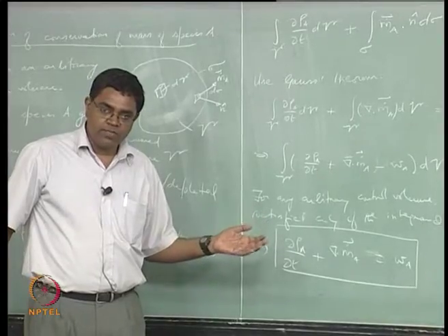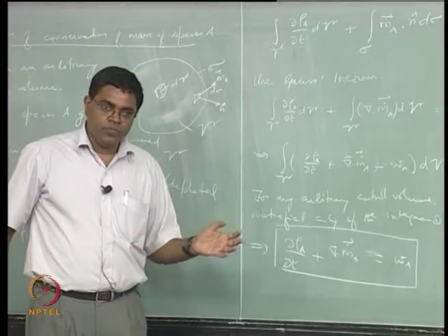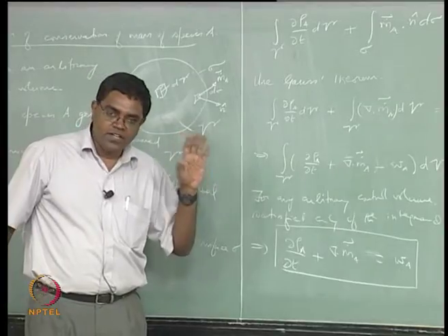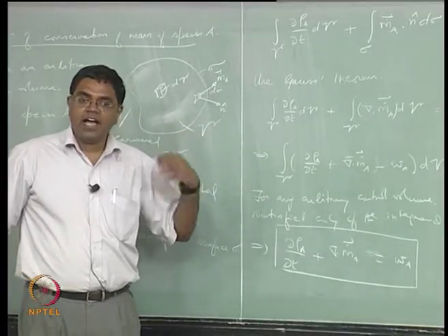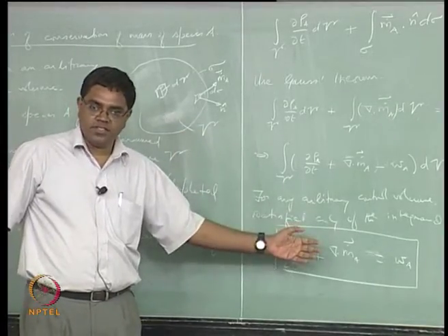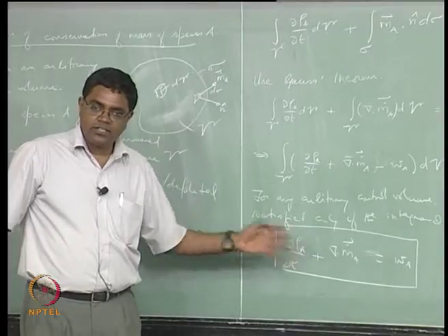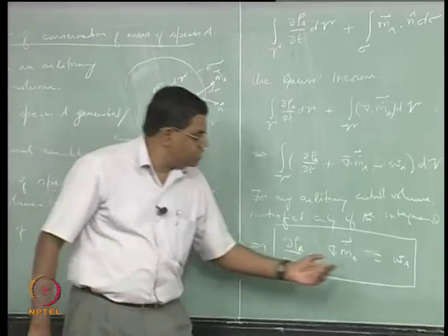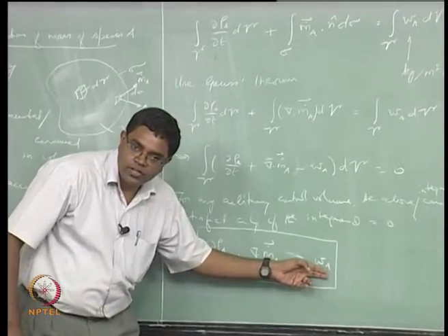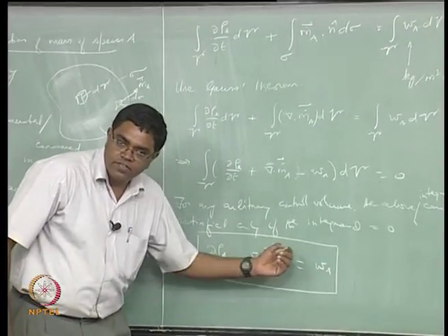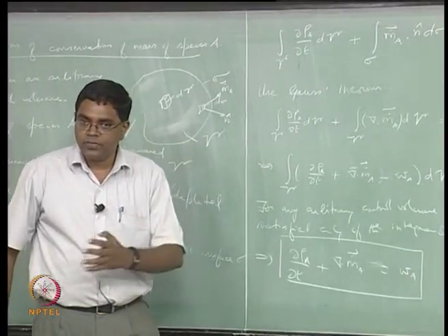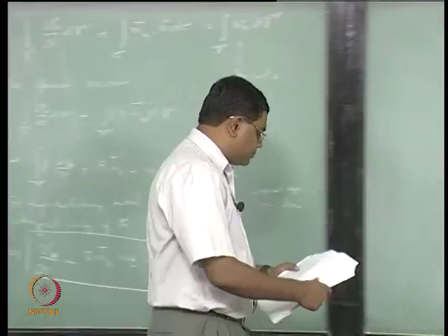And then we will have to split it into the mass average velocity of the mixture and its diffusion velocity. When you do that, we will get a convective term and a diffusion term separately, in addition to the reaction term that is showing up already. Then we will begin to see the three basic processes: convection, diffusion, reaction. So that's where we are heading.